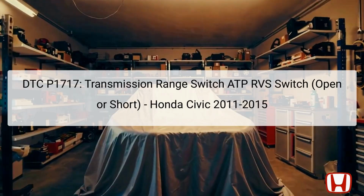The Diagnostic Trouble Code, DTC P1717, refers to an issue related to the transmission range switch ATP RVS switch, indicating that either an open or short circuit is present. This particular error code is relevant to the Honda Civic models from 2011 to 2015.